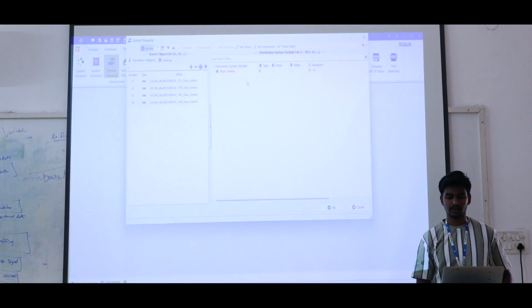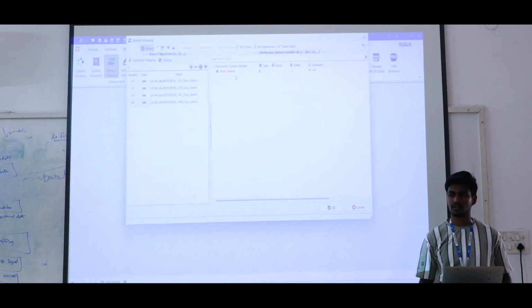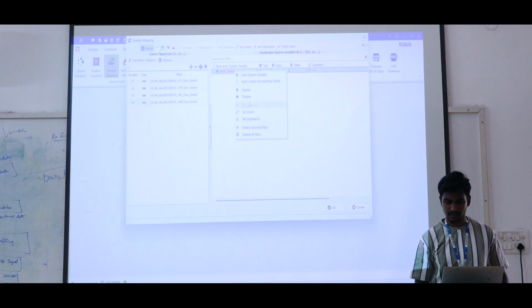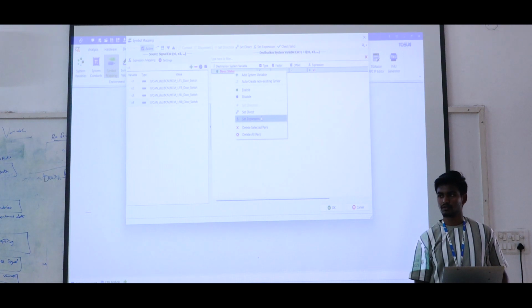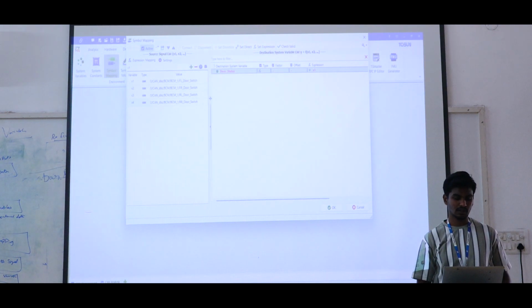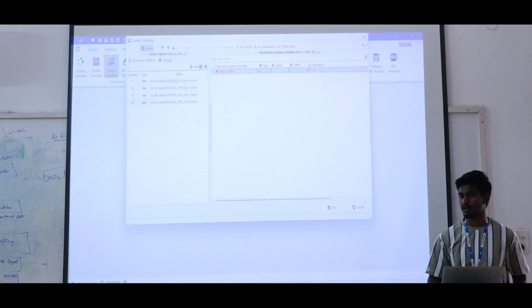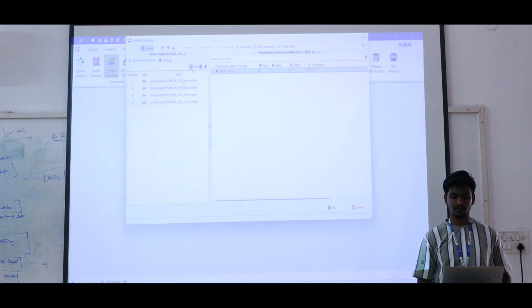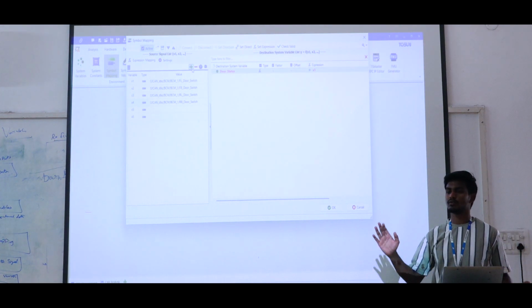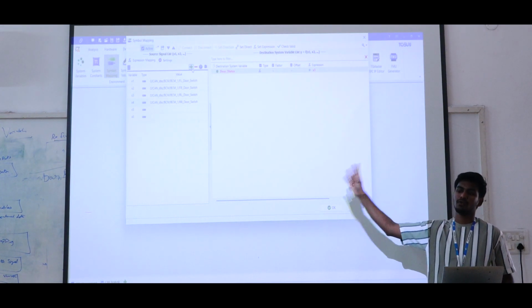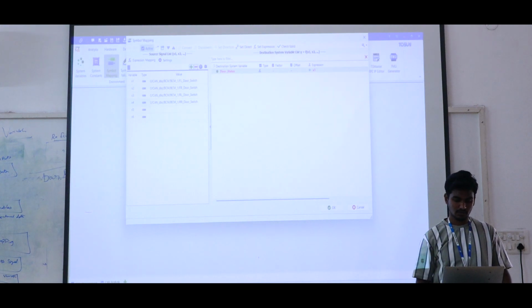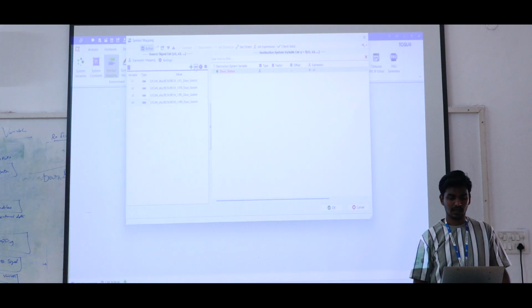So go to this symbol mapping, right click and add the system variable created, map door status. Afterwards, right click and then set as a set expression. So once you give the set expression, it is showing the left side variable and then the type of values also. Here we have the possibility to add different kinds of expressions also using the plus symbol for x1, x2, x3, x4, x5, x6. So now as per my requirement, you have to create 4 expressions. Okay. So using the plus symbol for 4 expressions and then click the value, it is showing the mouse pointer.